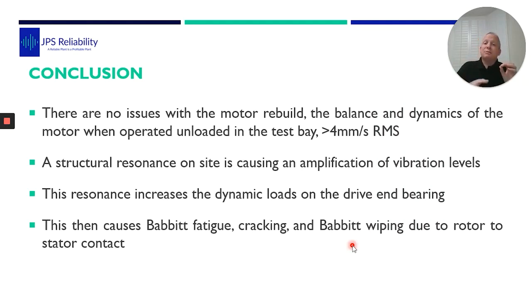But it's coincidental now that at the running speed, we're getting a structural resonance, which is amplifying the vibration, that is increasing the dynamic loads on the drive end bearing. This then is causing the Babbitt fatigue, cracking, and failure. Now, this is about 2017, so we've been going around for a couple of months.